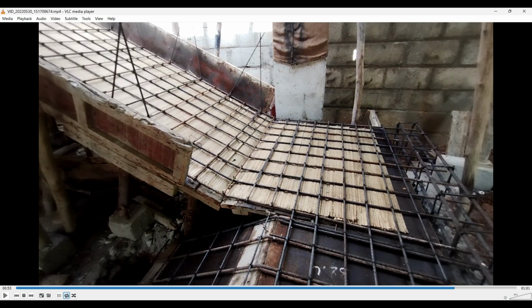If you were giving a top mesh, those two meshes will be separated by what? A chair. A chair will be placed between the bottom mesh and the top mesh. Okay, please keep that in mind. The way you execute the staircase will also depend upon many criteria, like the kind of support you have, if you're giving brick wall support or not, if you have a beam or not. What kind of landing do you have? It depends upon all these factors.